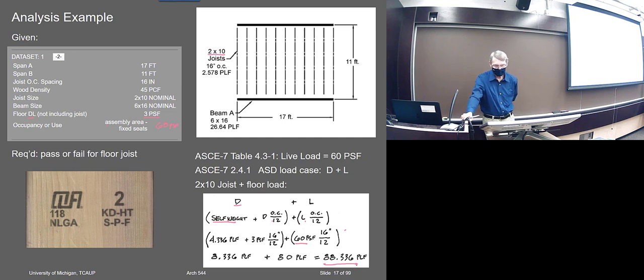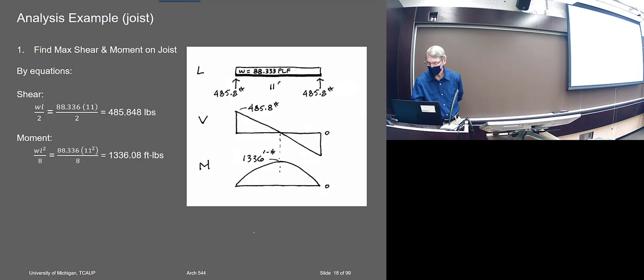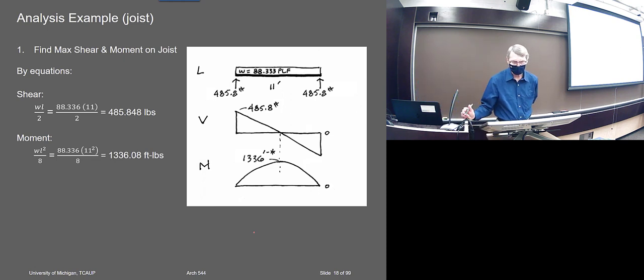88.33 PLF. So that's on one of these guys. Okay, so then the next step would be to calculate the forces that produces. If you want to make lovely diagrams, you can do that, or just do it with the equations. WL/2 would give us a shear. That would be the max, right? That would be this one.